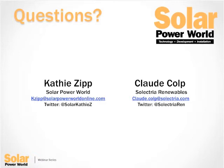690.125 code requires that equipment that performs the rapid shutdown shall be listed and identified. So someone's wondering who has certified or listed the rapid shutdown, and to what nationally recognized safety standard? That's a fantastic question. So the rapid shutdown combiner box has been listed. It's developed using listed components. I don't believe that there's a UL listing or an IEEE listing for the rapid shutdown test at this point in time.